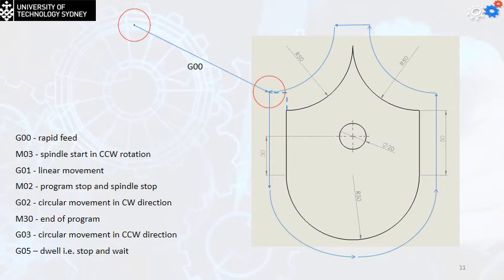Now, I'm going to do the cutting in counterclockwise. That means my next movement is going to be downward, but first I have to penetrate my cutting tool into the work part. So my next cut is going to be G01. The x and the y will remain the same. The z will be equal to, let's say, -10 if the thickness of your part is 10 millimeters.